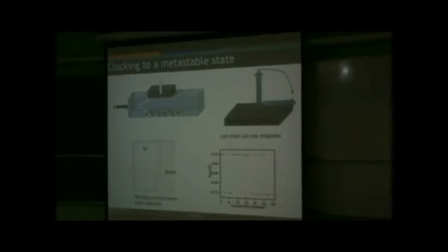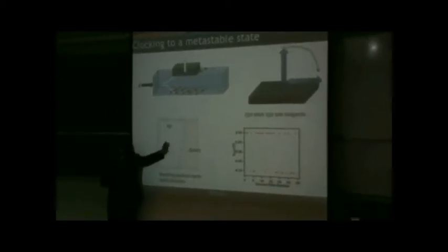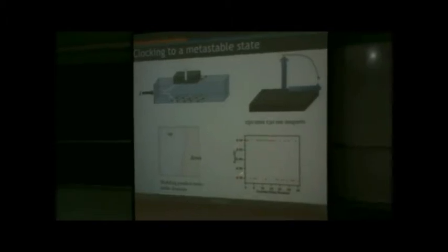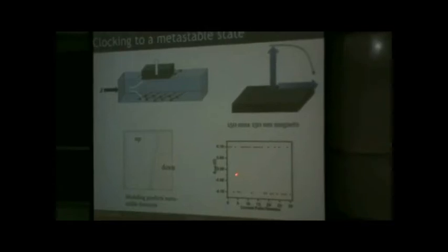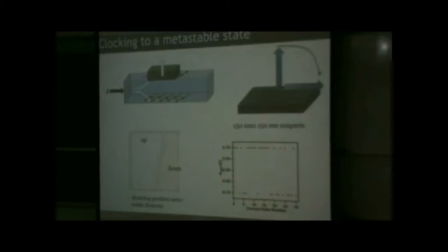Okay? So when we do a micromagnetic simulation, we basically find that when the current is on, the ferromagnet essentially breaks into some up and down domains, which is more stable. Experimentally, when we look at a 150 nanometer by 150 nanometer magnet, this is the data we see. So let's try to explain this a little bit. What we are doing is we are saturating the magnet in one direction, putting a current pulse, then going back and measuring where the magnet is. And as we keep putting pulses, we randomly get up and down directions.